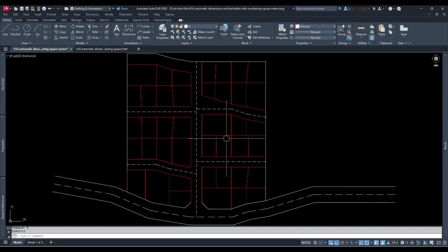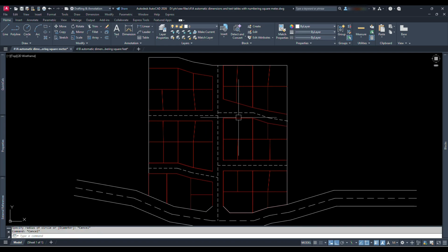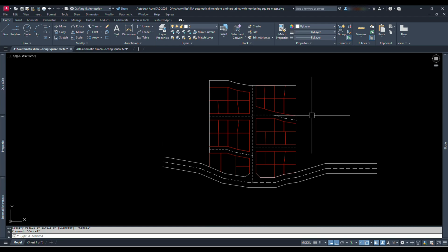If we don't make these settings before using the Lisp command, we might face some problems like extra large texts, or invisible small text. No proper display of dimensions. And we might have to go on changing the size or styles, which is tedious. So, these are the settings for using our first command. Our first command is PAD, which means plot area and dimensions. For now we are set.